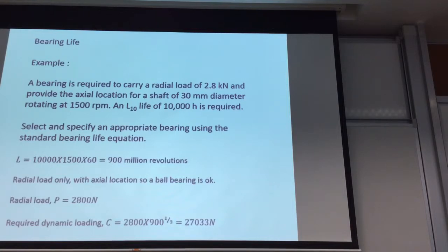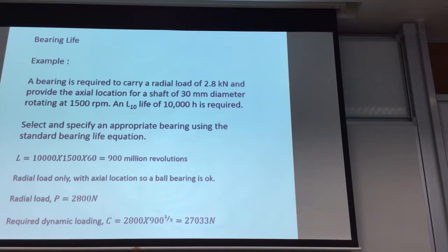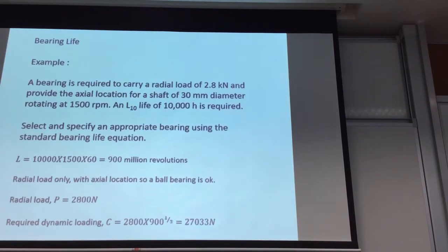So what you do, first you convert your lifespan to revolutions. You assume this is the value, you find the number of revolutions. You find your load from the free body diagram, which is that, E is that.